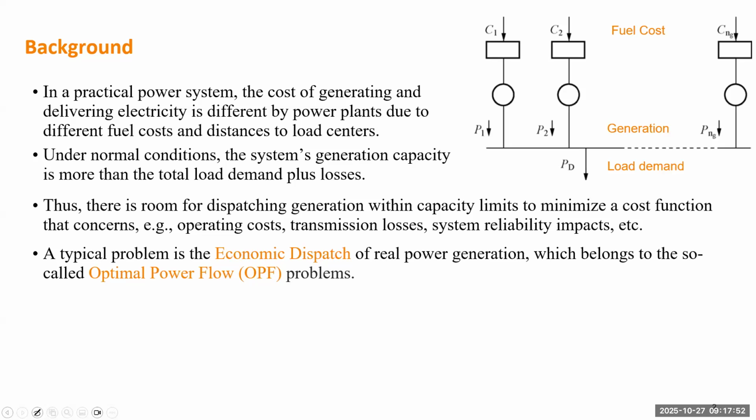So power flow is basically you just solve the power flow. For each bus, you know the type of the bus to be a slack bus, PV bus, or PQ bus. Which means for each type, you are given two variables: either voltage magnitude and angle, voltage magnitude and real power, or real power and reactive power. So you are given two of the four variables at each bus.